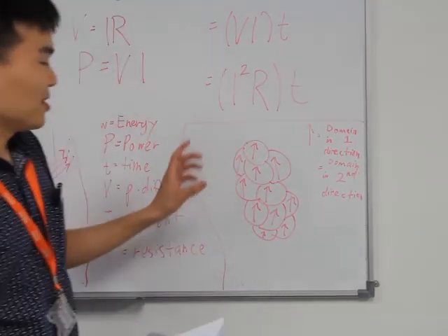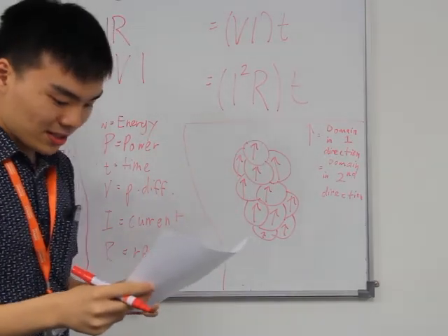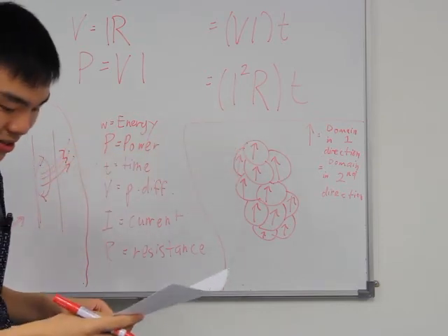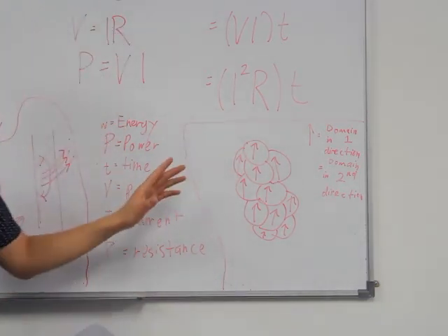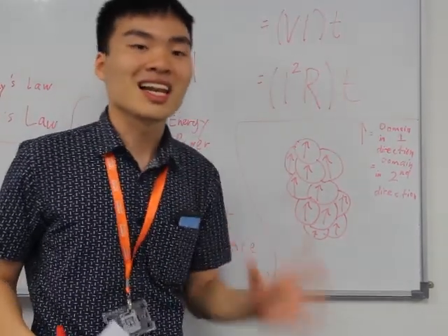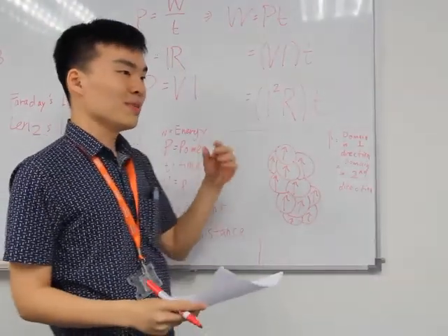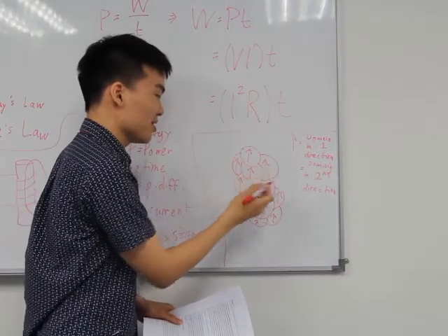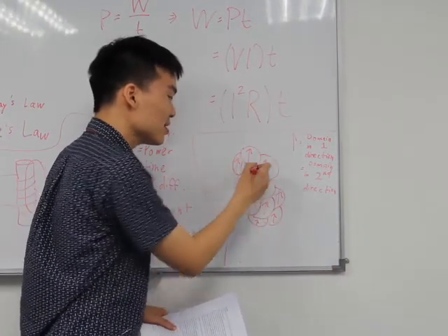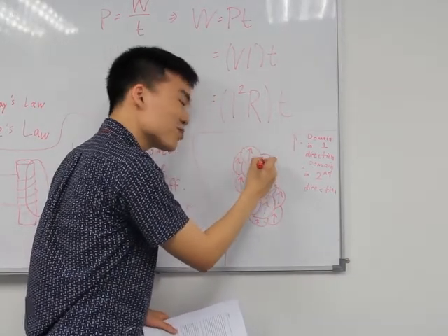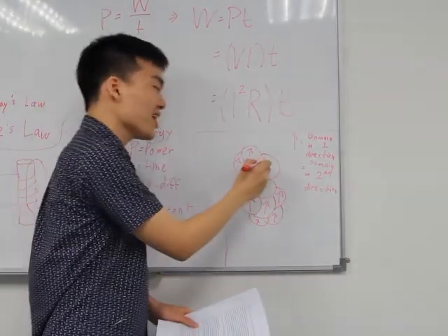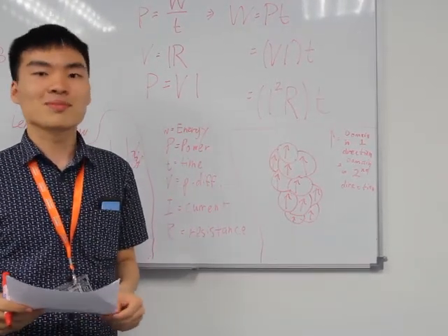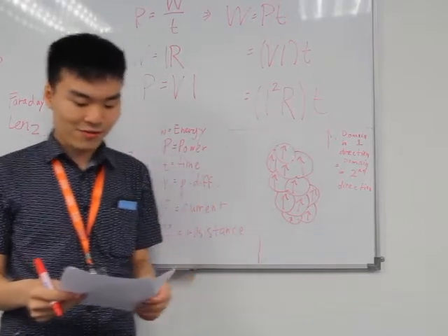And this will cause the change in size of the walls, the boundaries between the magnetic flux domains. They do that because they have to keep realigning with the magnetic field to be parallel with it, and they will catch against each other. Like let's say there are these two boundaries here. They'll try to squeeze past each other. They will catch. And they will snap, and it is this snapping which causes them to lose magnetic energy also in the form of heat.